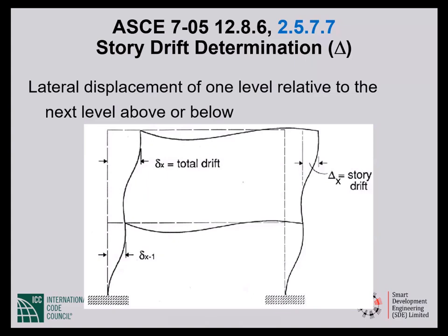If the non-structural components and the equipment supported on the roofs are not damaged, then there is reasonable expectation that the facility will go on functioning during and following an earthquake. There is a control of property damage aspect also to drift check. So this is beyond life safety.